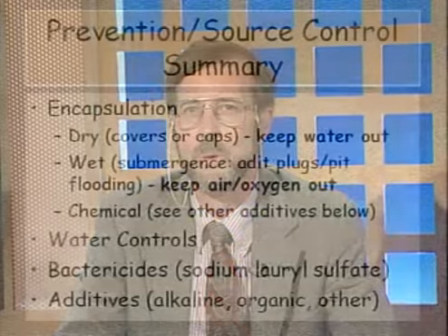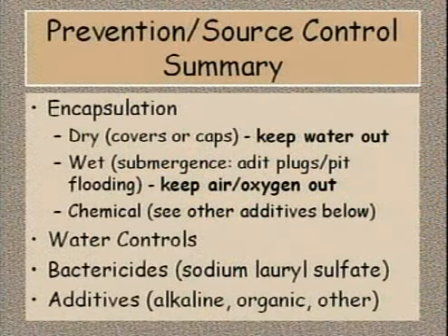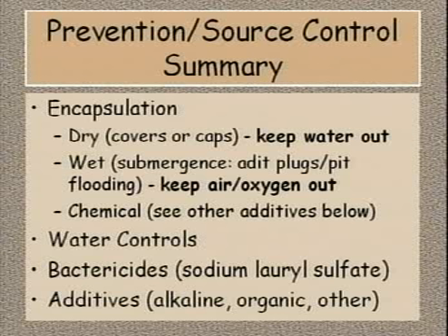This slide shows where we're headed in this segment on prevention. One prime ARD prevention technique that's been successful is encapsulation, which can be employed at a number of different levels. From a macroscopic level that includes covers and caps and waste submergence, down to the chemical level where individual grains of pyrite or sulfide are coated or treated in ways that inhibit the oxidation process. So which ones are the best? There's no clear answer because every site situation is different.